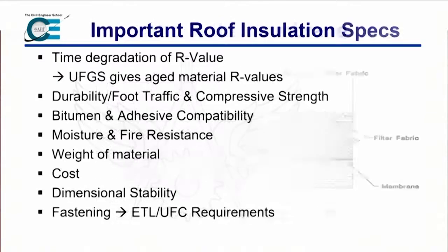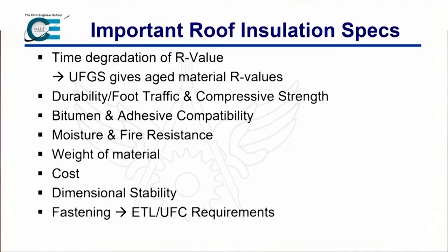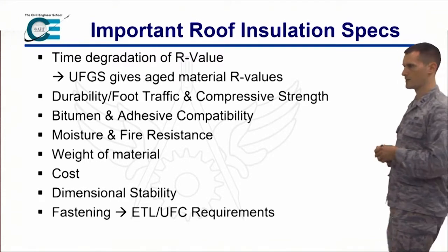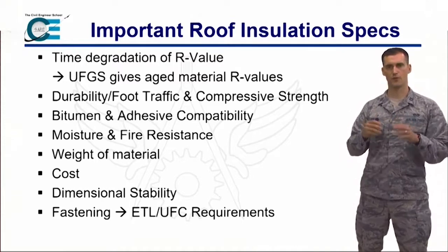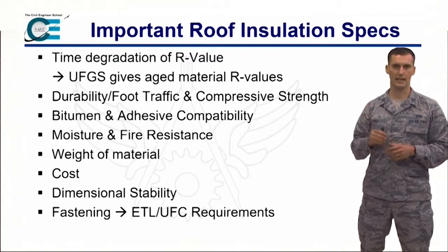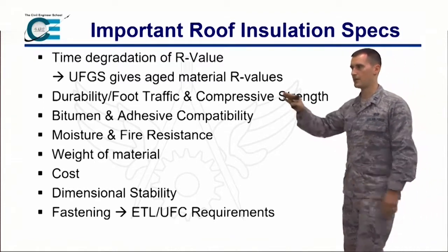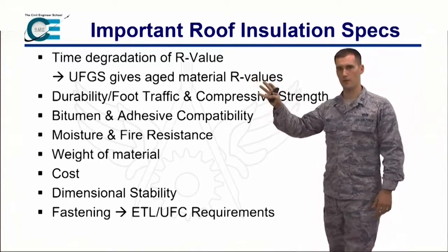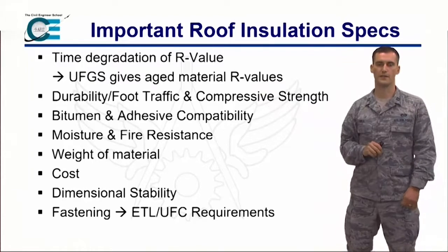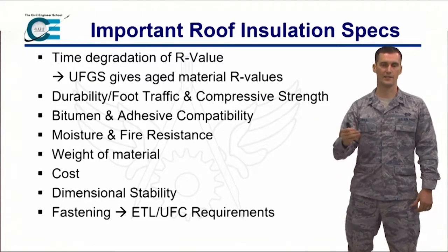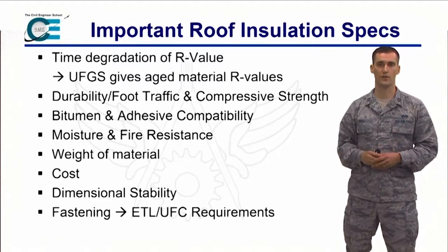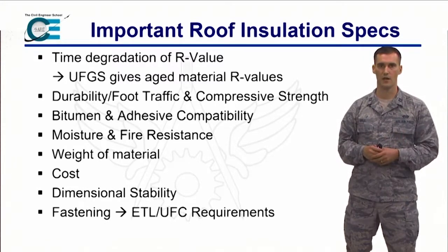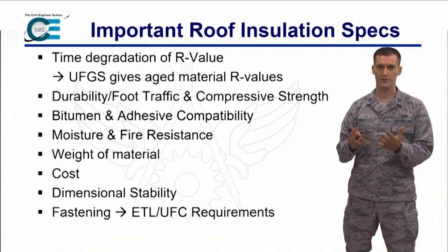So that's the broad overarching where we can install it. Let's talk specifically about the specifications, the things that we're looking at. In the next several slides, there's a lot of words on here which I'll try to hit the highlights, and a lot of them are for your reference going forward. I talked about the R value. The R value is really probably the most important factor with respect to how that insulation is going to perform, because ultimately that's what we're paying for. We're paying for how well you're going to resist the heat transfer.